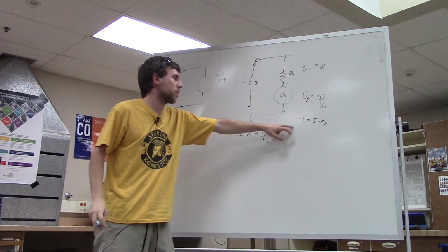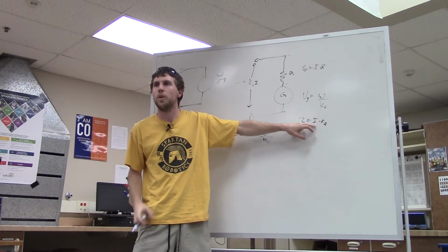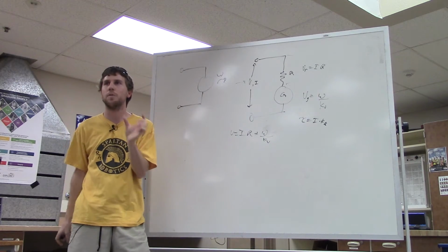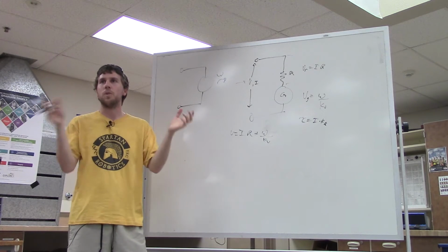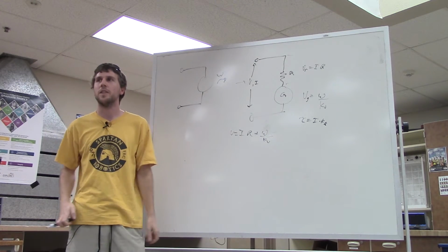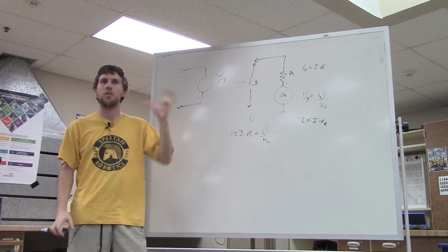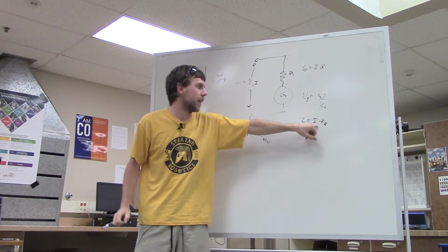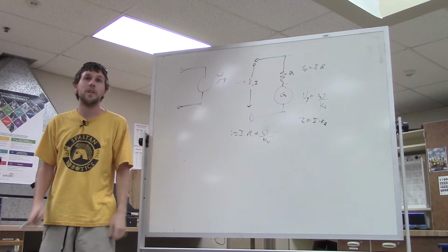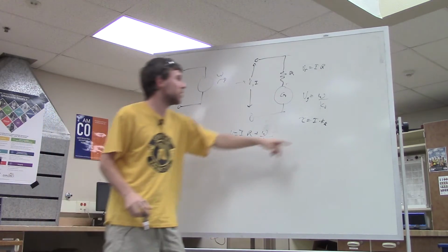Empirically, this is saying that the current going through the motor, so your motor is a bunch of windings which make up an electromagnet. The current going through your electromagnet will produce a magnetic field which will push on the magnets in your motor and produce a torque. So there's a linear relationship between the torque and the current. So yes, kT. These are constants.